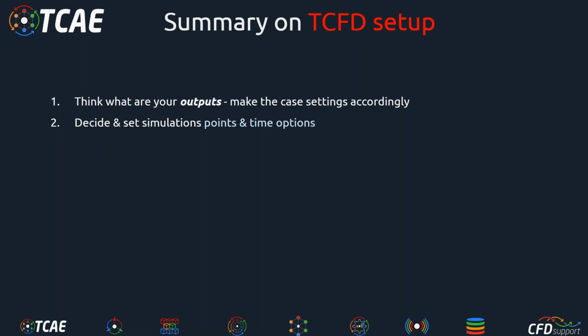What are your time options? Whether you want to simulate steady state or transient. Again, you can aspire to a very accurate simulation of one point, perhaps the best efficiency point, or you can be interested in the whole characteristics, whole maps, and their envelopes, and really complex simulations very early in the design process of your machine. So again, it's all about your goals, but in every simulation you have to decide what your points are, how many points you are going to simulate, and whether you're going to go for steady state or transient. It's perhaps the biggest decision concerning the TCFD setup.